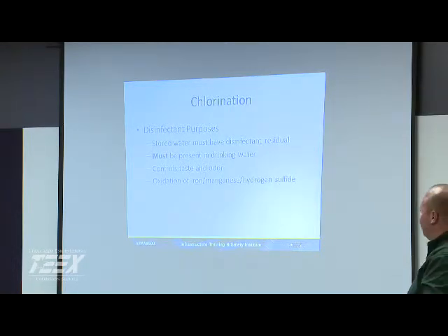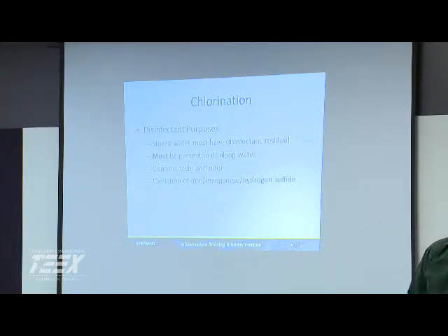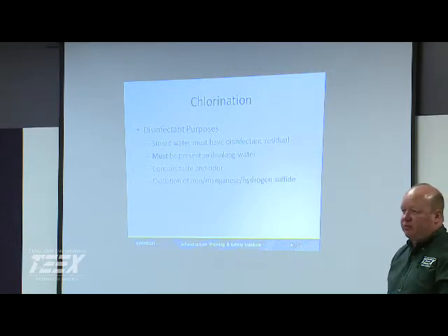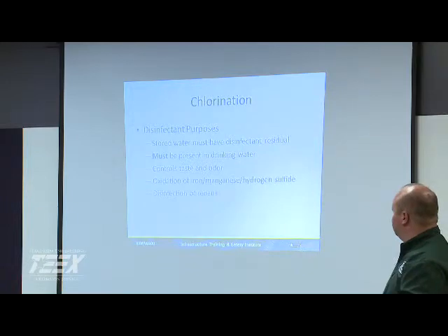One of the good things about chlorine is it'll help oxidize out a number of these components. Of course, the bad thing is if you're doing pre-treatment with chlorine, now you can have disinfection byproduct formation. So a lot of times you're using alternates as your oxidation.